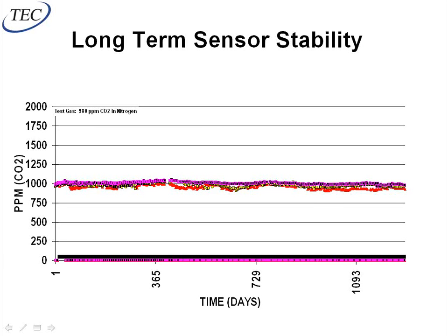So on a VAV system, what actually happens is the CO2 sensor wires to the VAV box. This is going to require a DDC style of VAV box controller. So the CO2 sensor wires to the VAV box. As I am approaching my CO2 set point, I start modulating my VAV damper open more to provide more air in there. And right now I've done absolutely nothing with the outside air damper on the air handler. I try to open up my ventilation damper, or my damper on my VAV box to get more ventilation air and steal that air out of the system.